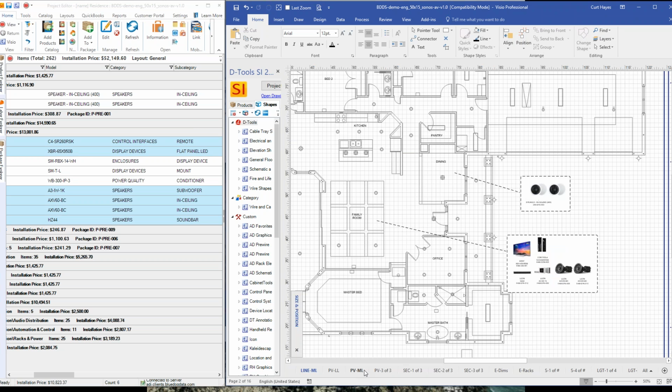Now, we consider this to be generally a pre-proposal or proposal phase thing. When the job gets signed and we actually go to engineering, the three most typical drawings that we do are the rough end plan for identifying all the wire penetration points, floor, wall, ceiling, and the rough end cabling associated with those, a rack elevation drawing, and a schematic drawing.